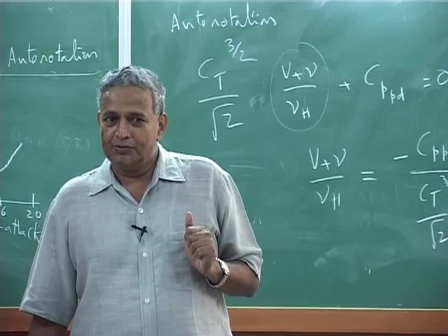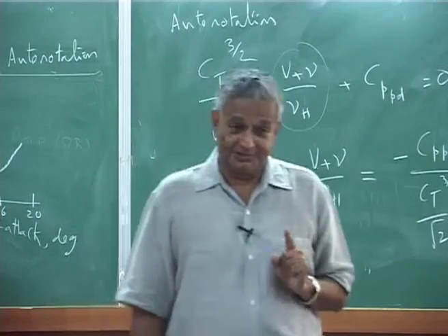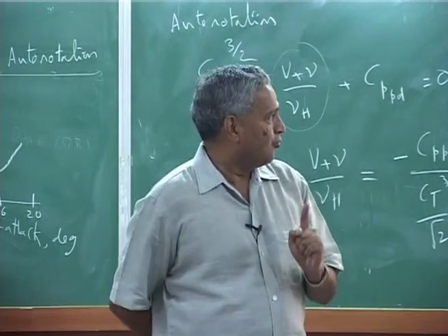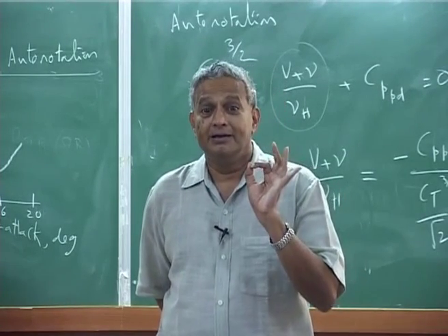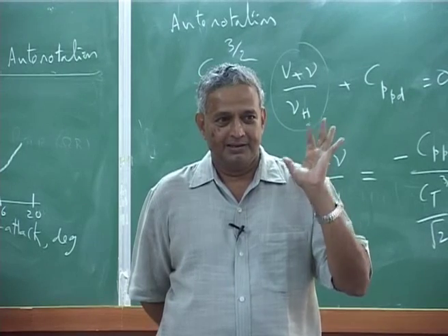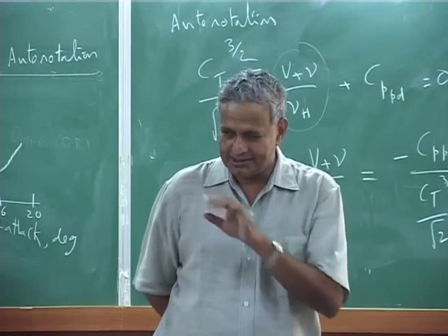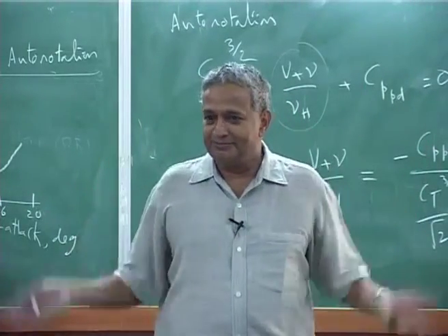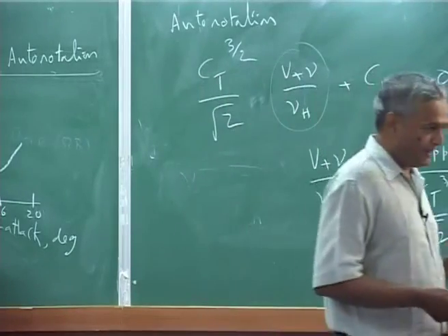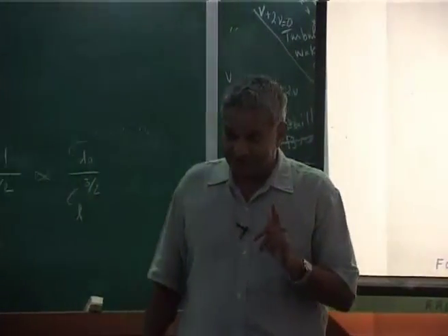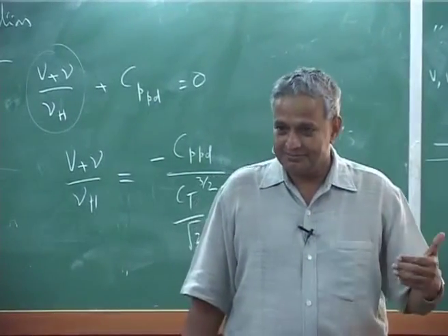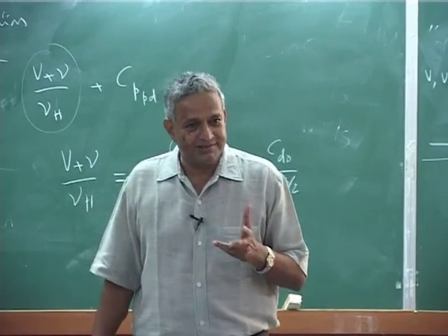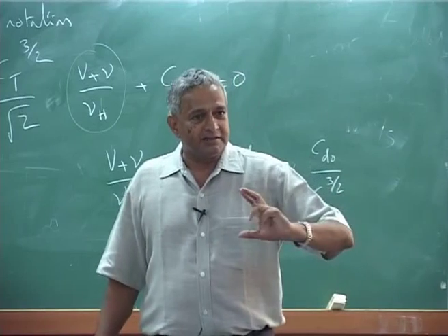So, there is a very interesting diagram that is purely based on forces acting on an airfoil in autorotation. Please understand, it is again a very simplistic approach, not with all the turbulence and vortex etc. Very simplistic formulation, but that curve is used for practical operation. But it is a very interesting curve, because autorotation, if you really see, is an equilibrium situation.